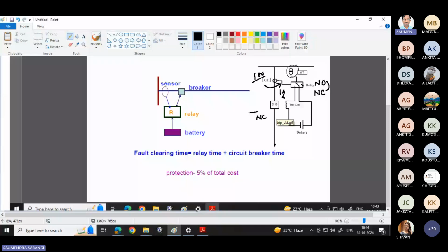In the circuit breaker, one contact is movable. When the trip circuit operates, the trip contact takes back this movable contact, and some sparking will come. Why does the sparking come? It is a simple circuit. Whenever we have an AC circuit with inductors and we want to open the circuit because there is a fault in the load side, then automatically there will be sparking, and because of the sparking, fire will come.